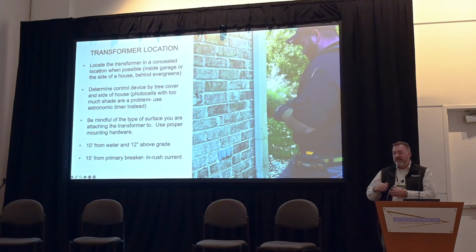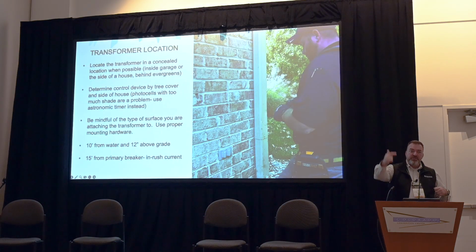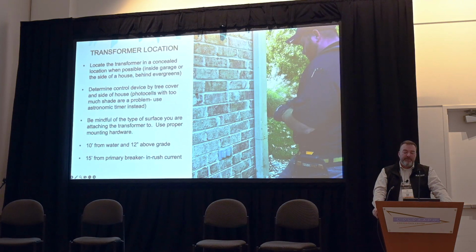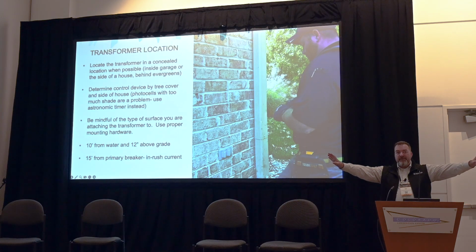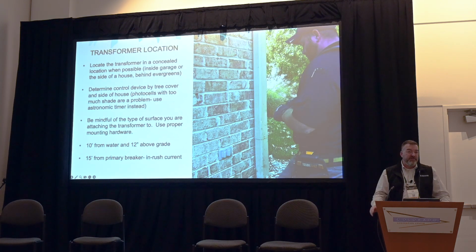What will happen is as power comes into that panel, as you kick those lights on, it's right there, right near the source, and sometimes that inrush flow can hit hard like a hammer and it'll trip those breakers because they're working on current activity. So sometimes you need a little bit of a slow ramp up of power to get to that transformer. When we put it farther back in a house, it has time to work through the circuits of the house, get back to those outlets, and it's usually never a problem.